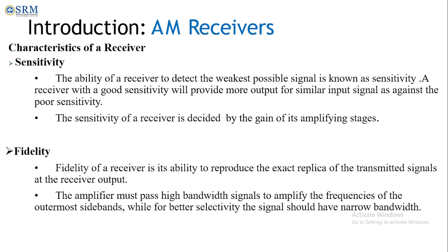The next thing is sensitivity. Sensitivity is the ability of the receiver to detect the weakest possible signals. A receiver with good sensitivity will provide you more output. The sensitivity of a receiver is determined by the gain of its amplifying stages.